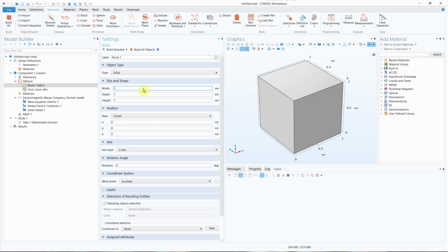In our case, we don't want it to be that small. Not only do we not want it to be small, we also honestly don't want to have to change it in this particular menu because we might have these sizes exist in other layers of our structure. And so we want to parameterize or turn this into a variable. So what I'm going to do is call this one unitW because that's going to be our width. I'm going to call this unitL. You can also call it unit depth if you wanted to. But that's going to be our depth.